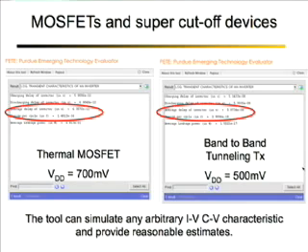On the right hand side, what I have is a band-to-band tunneling device, a carbon nanotube based band-to-band tunneling device that we have just used for the simulation purpose. The thing to note here is that these kind of devices can potentially have subthreshold slopes better than 60 millivolts per decade, and we have just provided the IV data into this tool, and this shows that the tool has efficiently figured out what would be the inverter delay, energy per cycle for this new kind of devices.